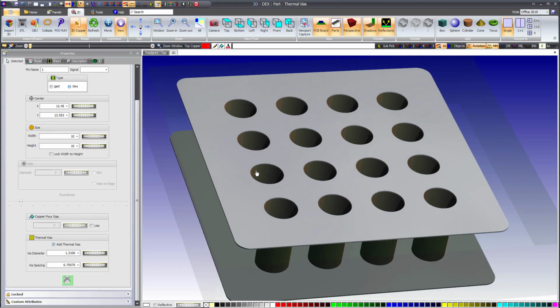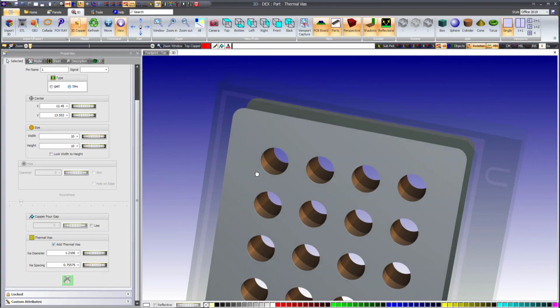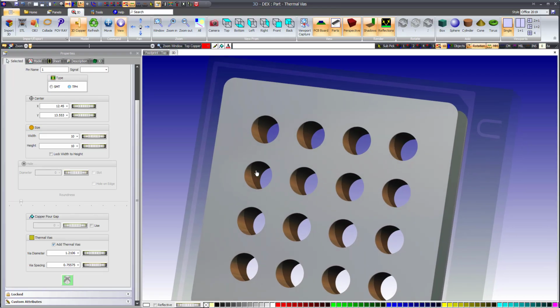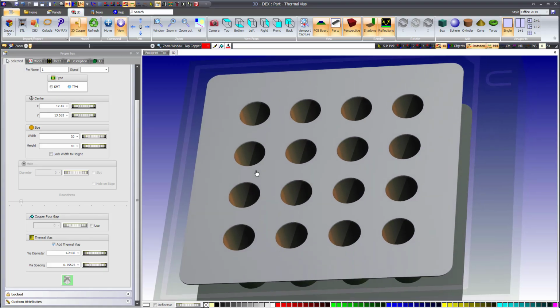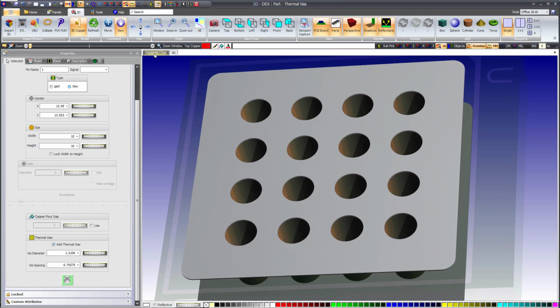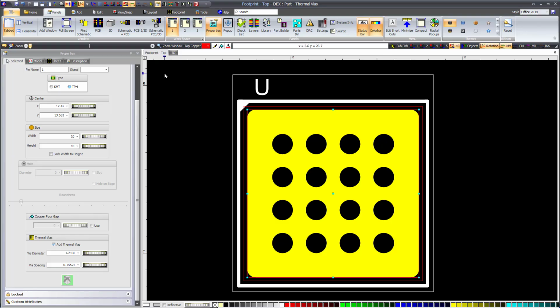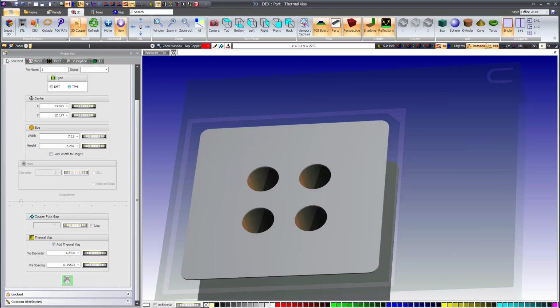They create a low thermal resistance pathway that allows heat to move efficiently away from the component. Heat can travel from the hot component on the top layer through the thermal vias into internal copper planes down to the bottom copper layer, and eventually be dissipated into the surrounding air or into an attached heatsink. By providing these additional thermal paths, thermal vias can significantly improve the thermal performance of a PCB and help keep components operating at safe temperatures.